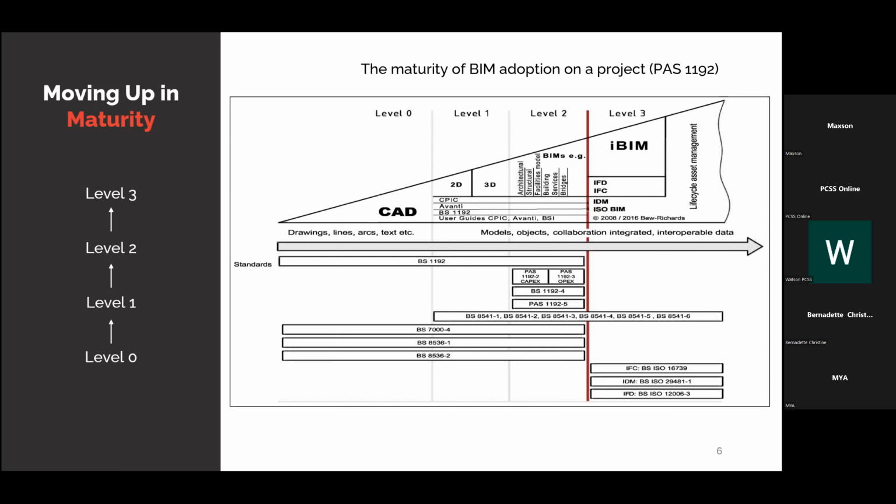And then we have one more level up, which is BIM level 2. This is at the moment the ideal stage of BIM, where every stakeholder, every discipline, whether it's architecture, construction, M&E, ICT, all the disciplines are collaborating using BIM technology and the BIM approach. So in this level 2, we normally have certain requirements. For example, we have to follow certain standards. Some of the famous standards are BS 1192, PAS 1192, and lately ISO 19650. These are standards that we can use as a guideline when we do a BIM level 2 project, when we collaborate.